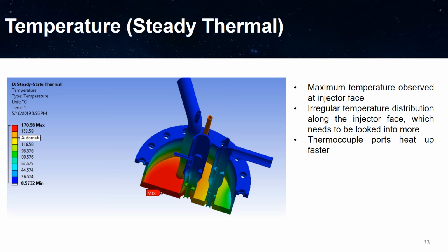Also, if you look into it, you can see that the temperature on the fuel lines is reasonably lower, because I already said that we're going to be flowing fuels through there. Instead of convection we just gave a constant temperature, because we have different fuels going in and different film temperatures and film coefficients occurring at different times.